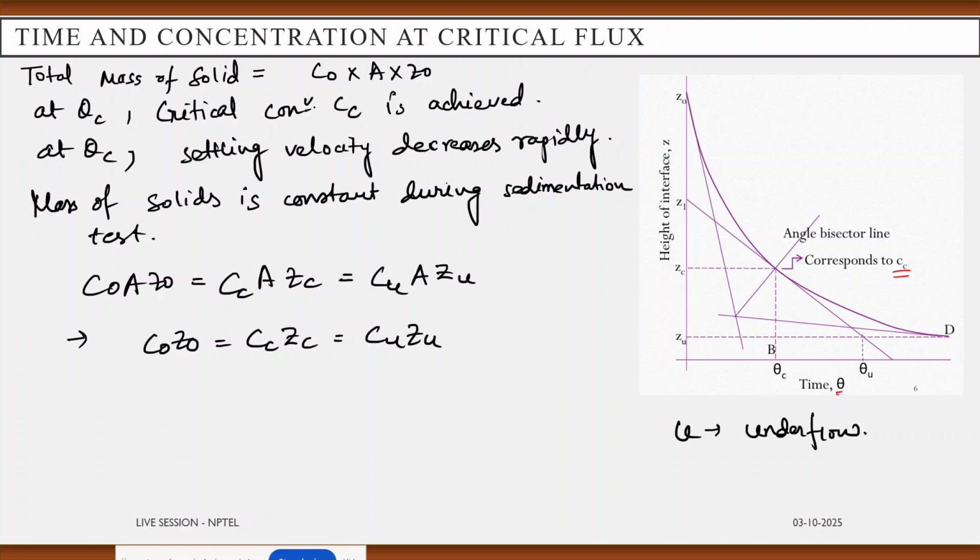So when the sedimentation test is happening, the solids are getting settled down at the bottom. So in that displacement procedure, we are continuously displacing the water from that slurry to the upward of the thickener.